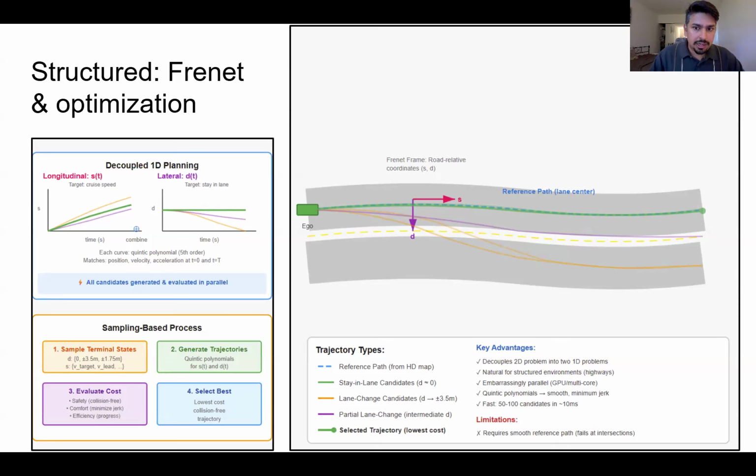The really good point of this is that you do not run a search over successive states. You can parallelize pretty much all of this process, from generation of the motion primitives to even the actual costing. And this is where modern GPUs can be used, and you can move a lot of your actual computation onto the GPUs as much as you can. And if not for GPUs, you can also just use your CPUs, multi-threads and multiple cores to parallelize most of these actions that you have, or most of these samples that you have, because they are independent.